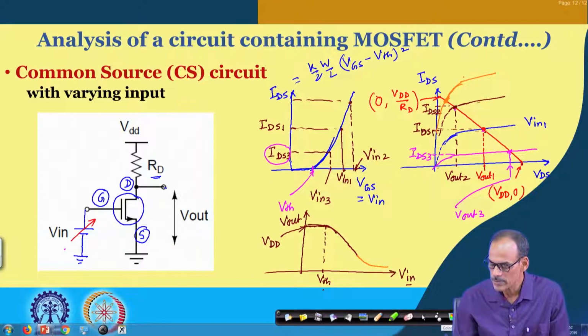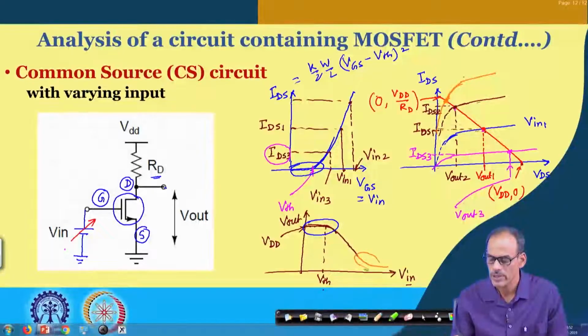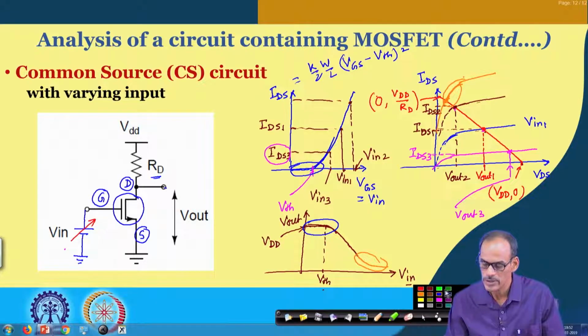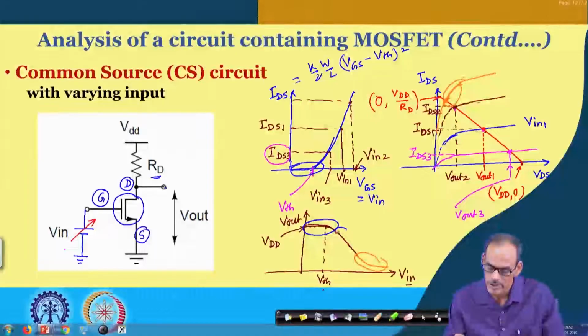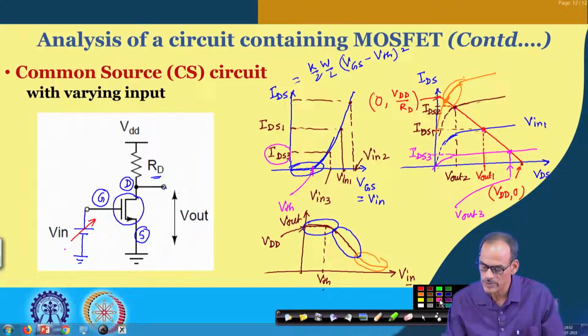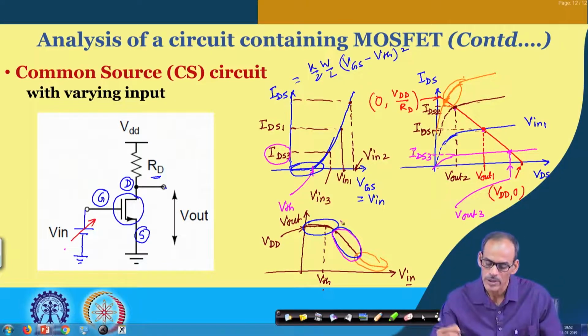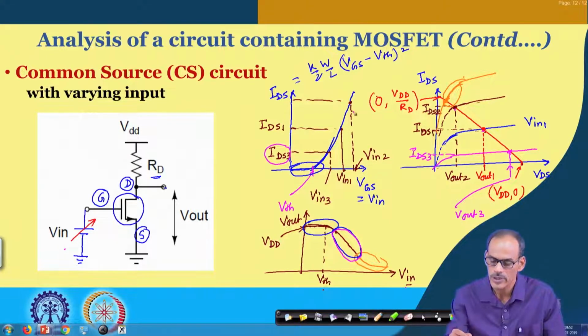So, here you may say that this nonlinear portion is due to this part, and on the other hand this nonlinear part of the characteristic curve is due to the device entering into the triode region. And in between you can get a nice portion of the characteristic curve, namely this portion. Let me use a different color for this part. So, this portion is a very good part, namely if I change the input here, then the corresponding current variation here is fairly linear with that voltage, and here of course, the load line is linear. So, that makes the input to output relationship fairly linear.